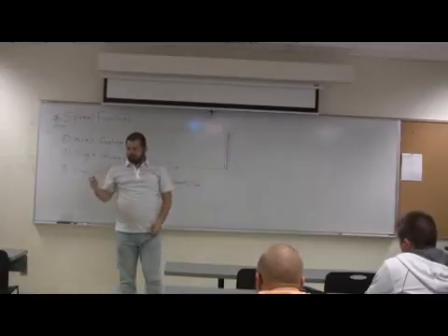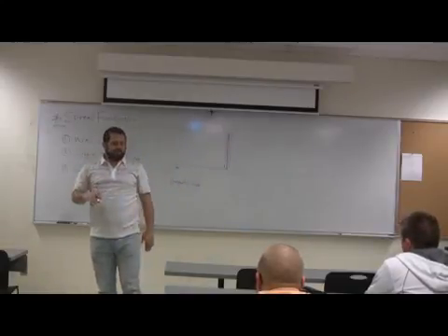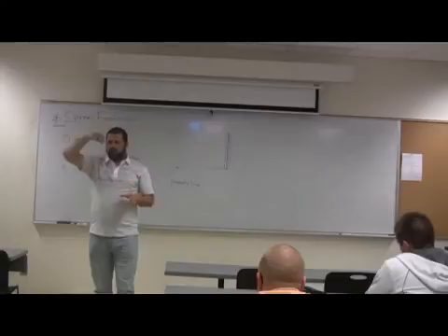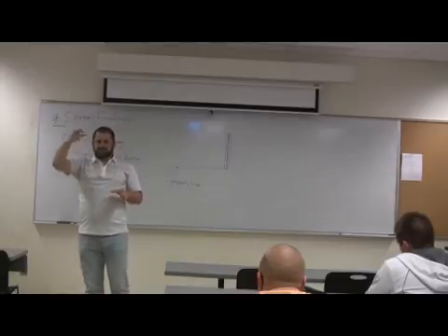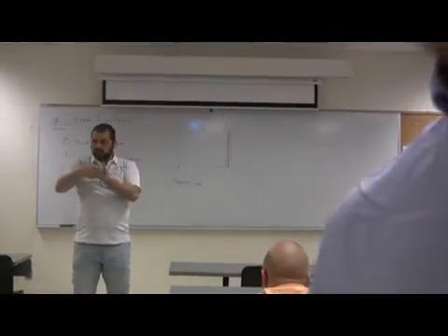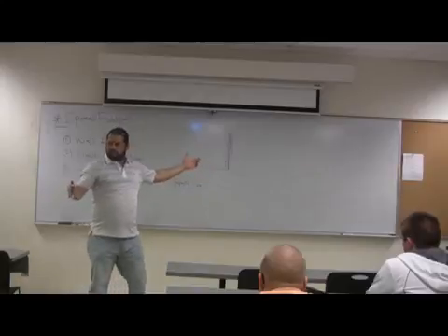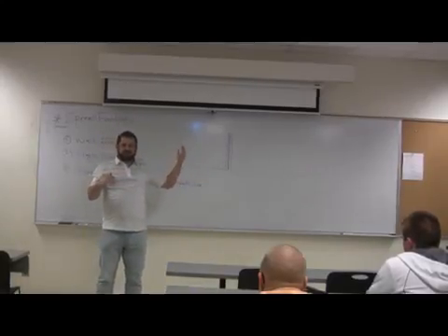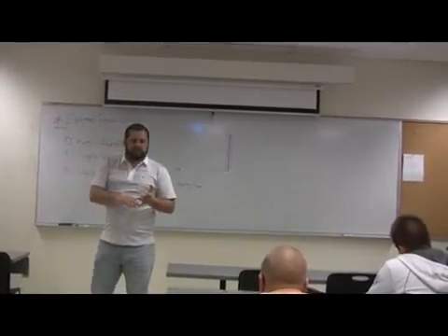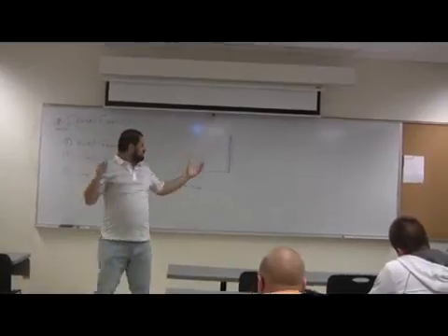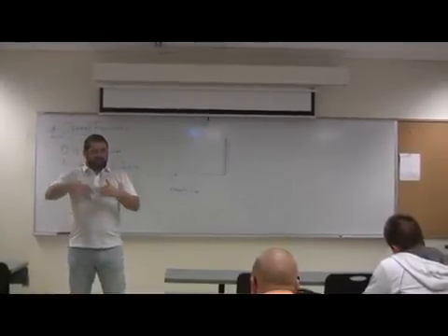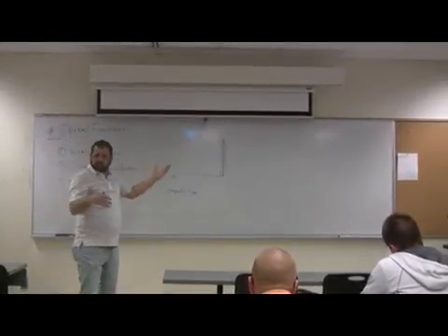So when you design a wall footing, basically you are finding the width and the depth, because that footing will be continuous along the length of the wall. So the loads coming on the wall footing will be per foot strip. So your footing will be 1 foot by the width, and depth. When we say design, we're always talking about the cross section, like B and H in beams, and the reinforcement. Here, for a single column footing, we will be looking for the area, the depth, and the reinforcement in each direction. That's what we need to design.